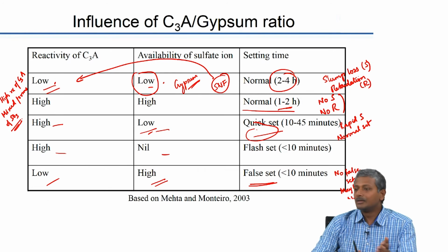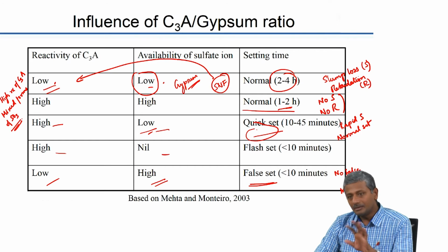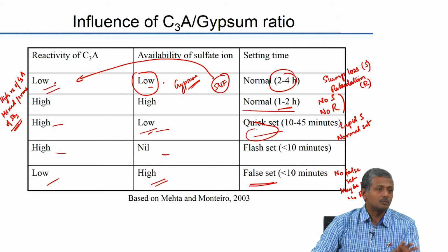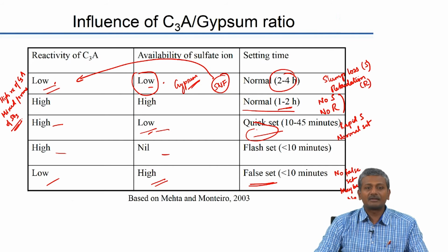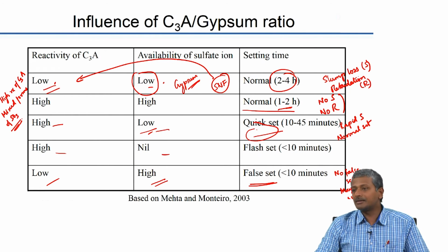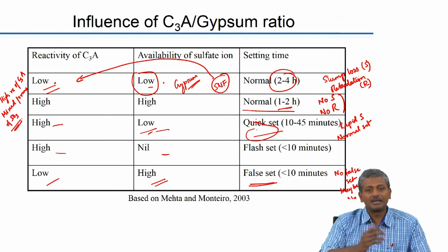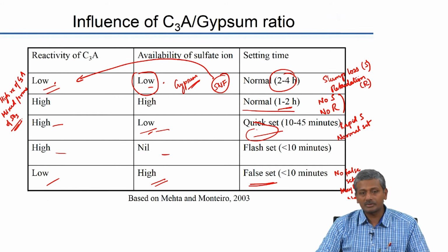Even in that case, your grinding of the cement, all that also still will have some effect in altering the compatibility of the system, but for the most part use of a high reactivity C3A and a mixed sulphate availability in your system in terms of anhydrite and hemihydrate contributing sulphate rapidly and gypsum contributing sulphate in the later stages, that will lead to an effective performance in your cementitious system.